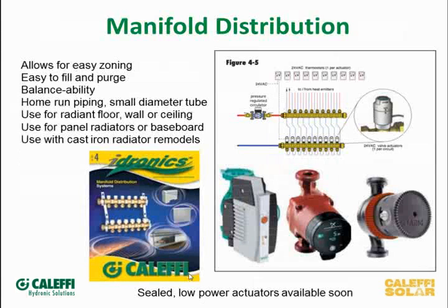Another thing that's becoming really popular, and it works really nicely with these zone systems like that, whether you're using the actuators or the thermostatic radiator valves, are these delta P pumps. So now that gives the pump the ability to modulate based on how many zones are opening and closing. So again, it just increases the efficiency of the system. They use quite a bit less power, and being able to modulate down at lower speed when only 1 or 2 zones are calling saves you some additional power consumption. Because really in the end, we're looking to save energy both in the electrical distribution side of it, what it takes to run the pumps and the controls, as well as the heat emitters with the heat pump or the solar component.